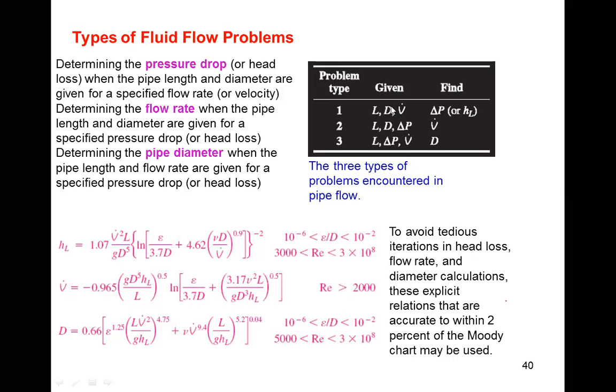That is only because some vapors are present in your pump impeller or casing, and your pump is not designed for vapors, it is designed for liquid. So sometimes pumps burn out. As you might have seen in older times, the pump needed to be put nearly 30 feet down in the ground, so that it has two reasons. One is to minimize the suction height, which we will talk about later on.